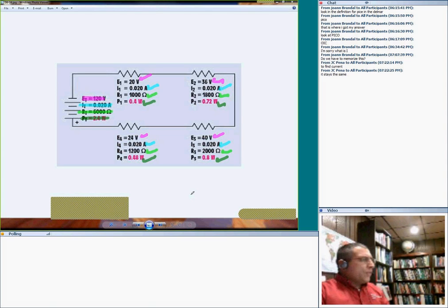Now, friends, you must be able to analyze this circuit. As I said, the hardest part, guys, is to know where to start. If we started by finding R2, because everything else is about R, and then from the total voltage and total resistor, we find the current.